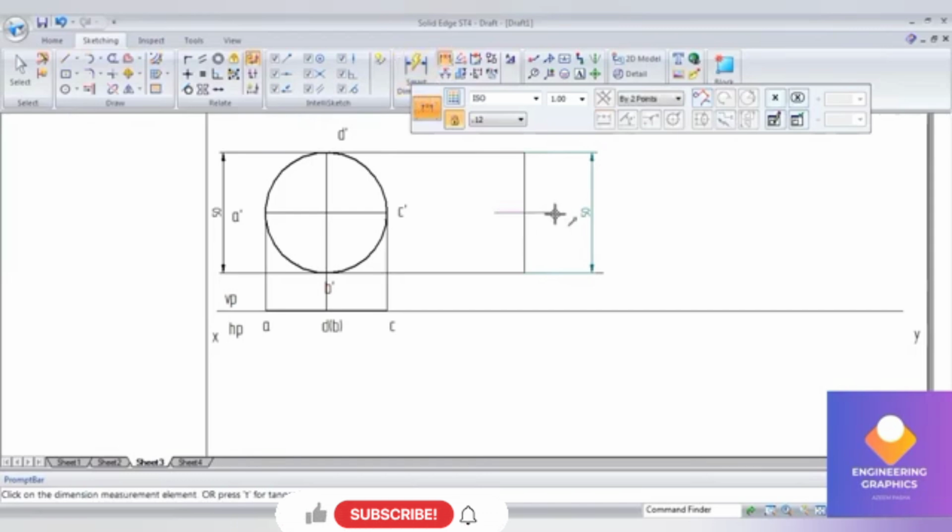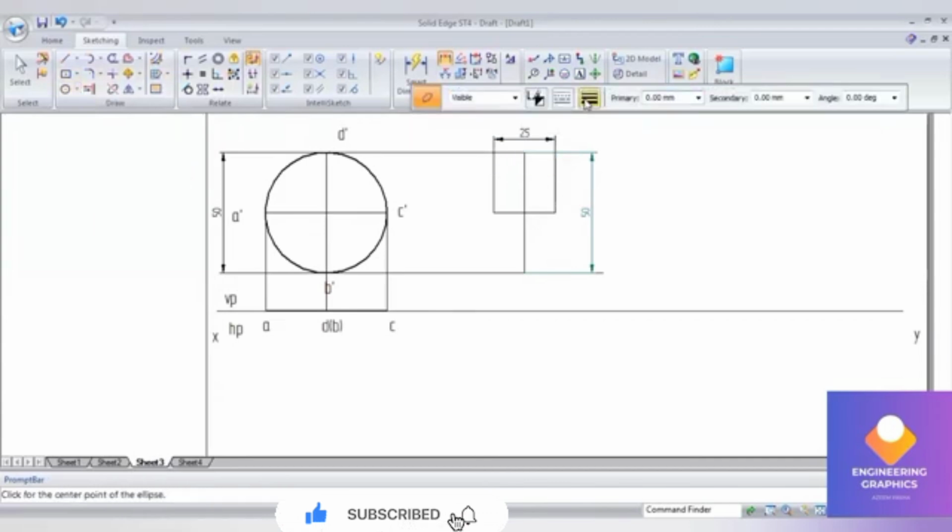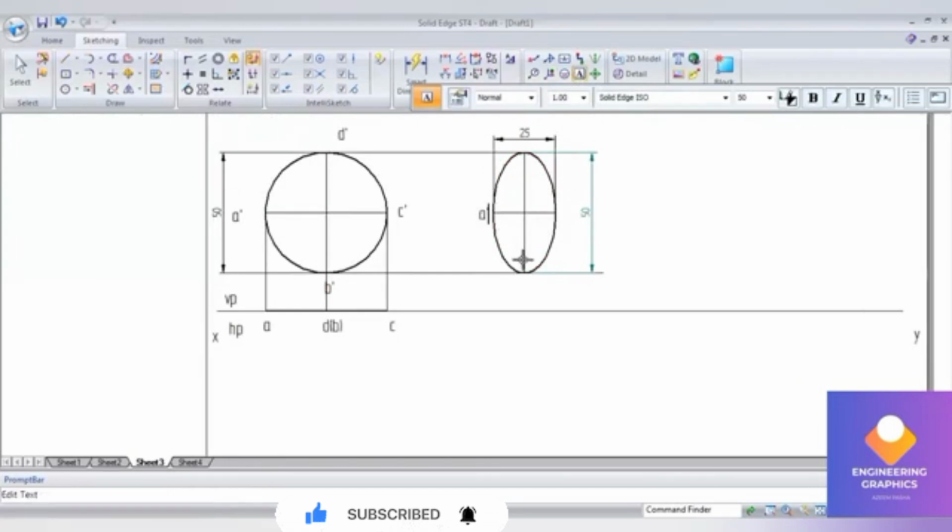So go to distance between command. So now you can go to the ellipse by center point. So from the center point, take major axis dimension and the minor axis and construct the ellipse here. So ellipse is constructed with the major and minor axis here. But we don't know the angle. So to find out the angle in the top view, we have to find out the angle here.